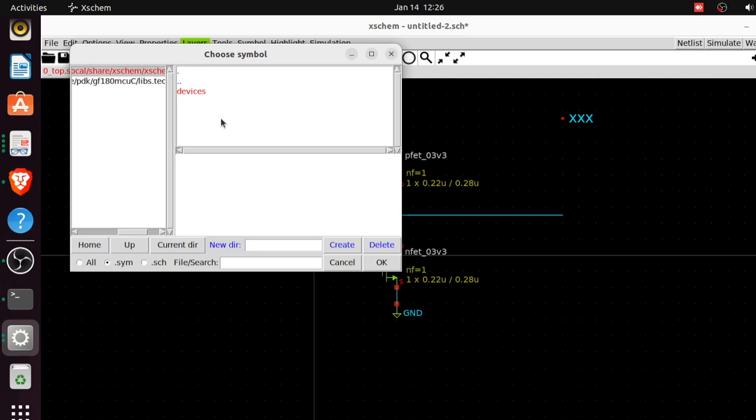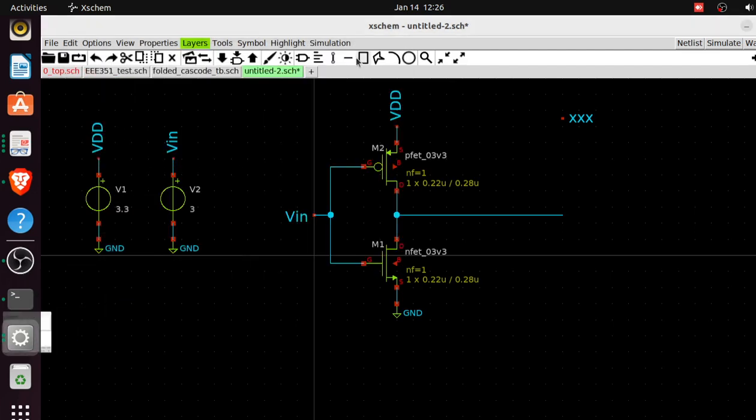Remember I said the CMOS will be in an environment full of capacitive loads. Because this is an inverter, most likely what will be connected to the inverter may be other gates, maybe NAND gates for instance, and the input of a NAND gate is capacitive, because the NAND gate will be made up of MOSFETs, right?